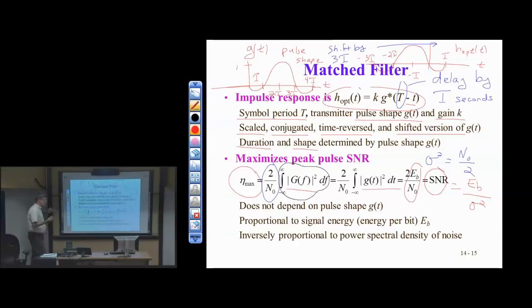Different systems have different SNRs. I'll just give you a couple. In wireless scenarios, in mobile cellular, it's in the -5 dB to say 15 dB range. Could go to 20, depending how close you are to the base station. For power line, we go from -5 dB to 5 dB. For DSL, we go all the way up to 60 dB. It's a much nicer environment in DSL. It's twisted pair, which isn't shielded, but twisted pair. Cable is even better with coaxial cabling. The SNRs are also in the 60 dB range.